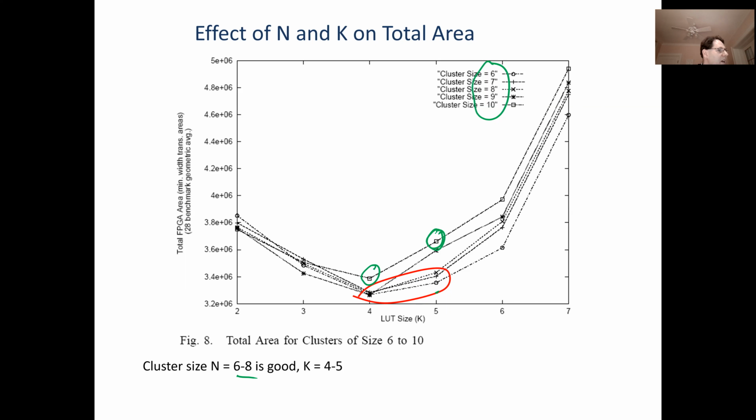Yeah, so because of the cost and the area of the inputs, it's exactly right. Like the local routing is getting very expensive. So local routing is being built as a crossbar, right? So on every single LUT input, so on k times n LUT inputs, we have a mux, which has n plus I inputs.